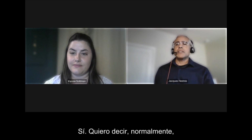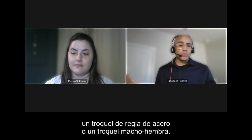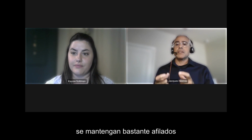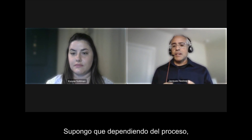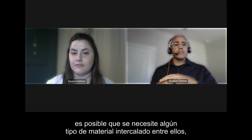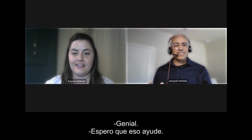Typically you could use anything from a rotary die, steel rule die, or male-female dies, which work well. In this case, just make sure that the dies are maintained quite sharp, and that they're striking the membrane on a hard surface. Depending on the process, you might also need some type of interleaf material where you sandwich the membrane in between, so that it can cut cleanly just the edges of the membrane. Great. I hope that answers the question.